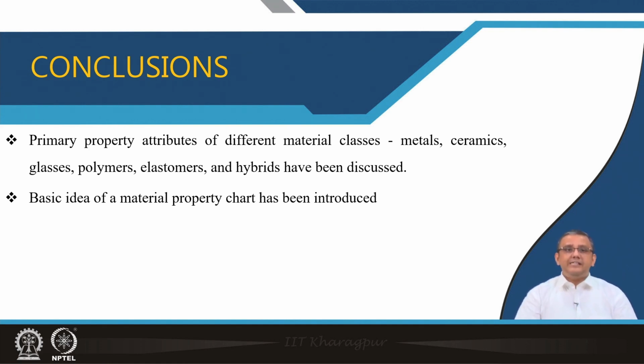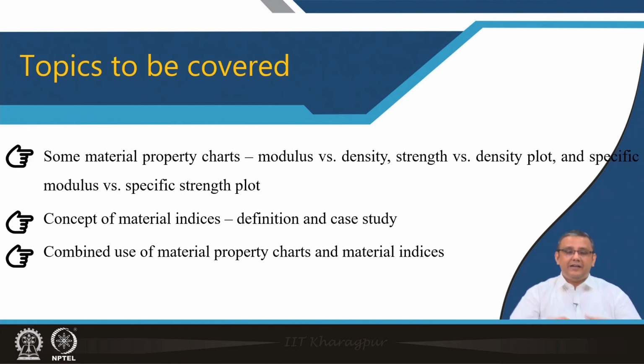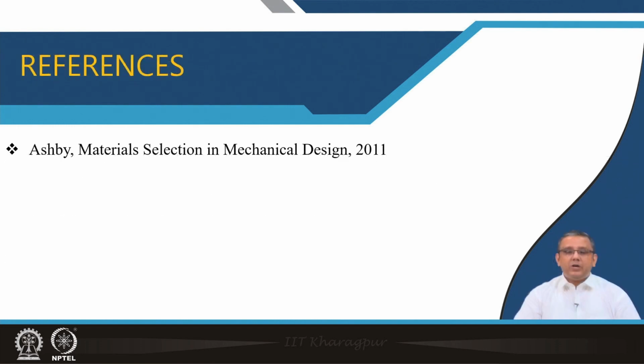We also discussed the basic idea of a material property chart in the form of Young's modulus over density, and in the next lecture we will cover some more material property charts like strength over density, specific modulus over specific strength, and then we will move on to the concept of material indices and define how material indices play a very important role in hybrid material design. The topics of this lecture have been taken from the